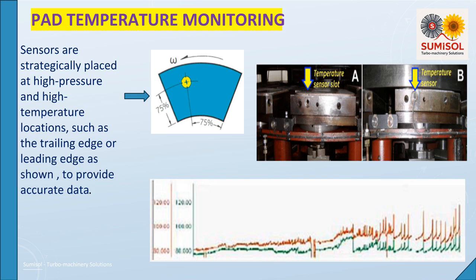Bearing temperature excursions can cause operational disruptions. Below are some noteworthy bearing temperatures based on operational experiences and ASTM B23. 110 degrees Celsius alarm temperature, 120 degrees Celsius trip temperature, 132 degrees Celsius babbitt creep, 232 degrees Celsius babbitt melting point. It is important to watch for a sawtooth type trend of bearing pad temperature, shown in the picture below, which can be a telltale sign of a lubrication issue.